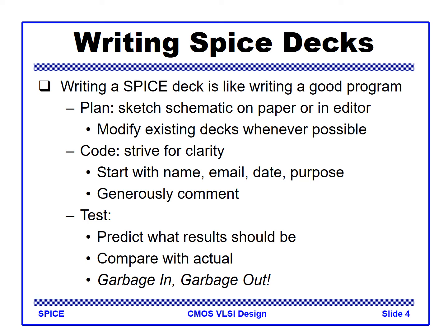That's the mistake most students make. They rely on the simulation too much, because in such cases, the student may not set up the simulation environment properly. So you have to be aware of what the result should be before you actually simulate.